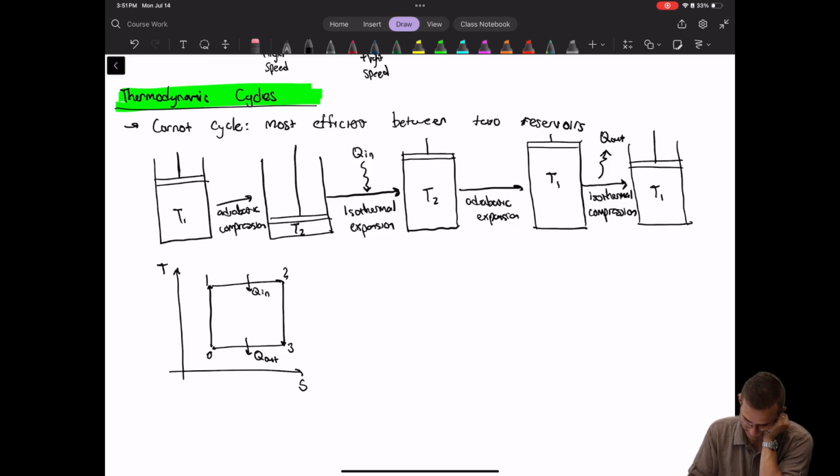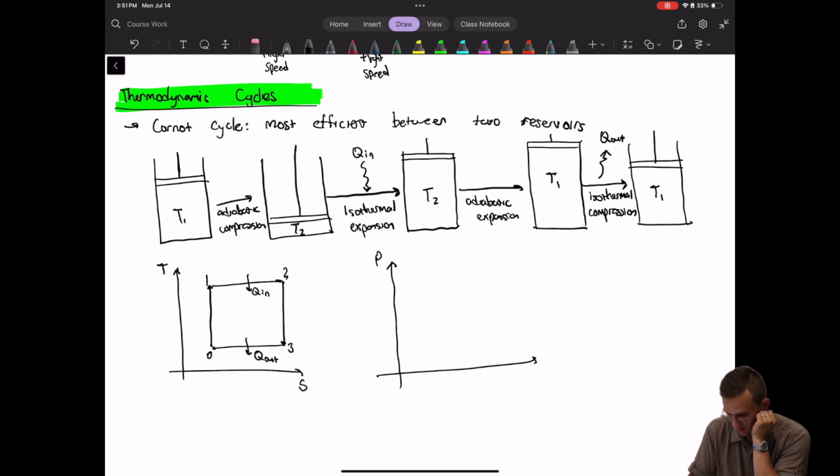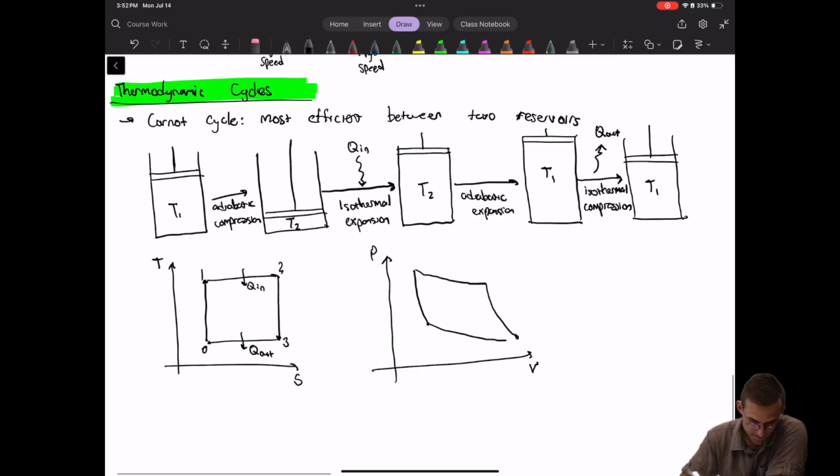The PV diagram, you see the sort of isentropes and isotherm processes. So you start at 0 here, and you're going up adiabatically or isentropically. So it's a little bit steeper, and then you get a 1 over V for the isothermal branch, and then it's like this down to state 3, and then you get that isothermal to complete there.